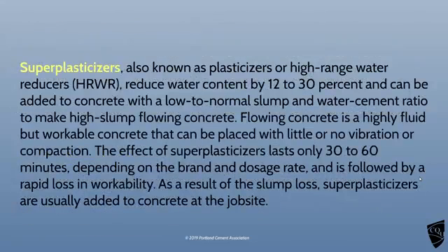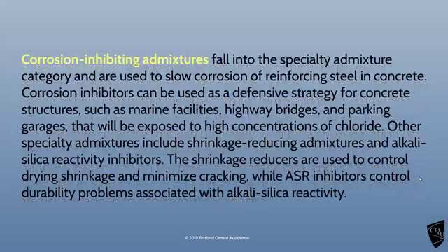Super plasticizers, or just plasticizers, they reduce water. You can reduce it by, look, 12 to 30%. This comes from the Portland Cement Association, you see at the bottom there. Gives you a low to normal slump. Don't panic, it's coming. You get a very liquidy, very fluid but workable concrete. You can pump concrete this way, but they only keep it plasticized, running, for up to an hour. After that, it doesn't work anymore, so you've got to be pretty quick.